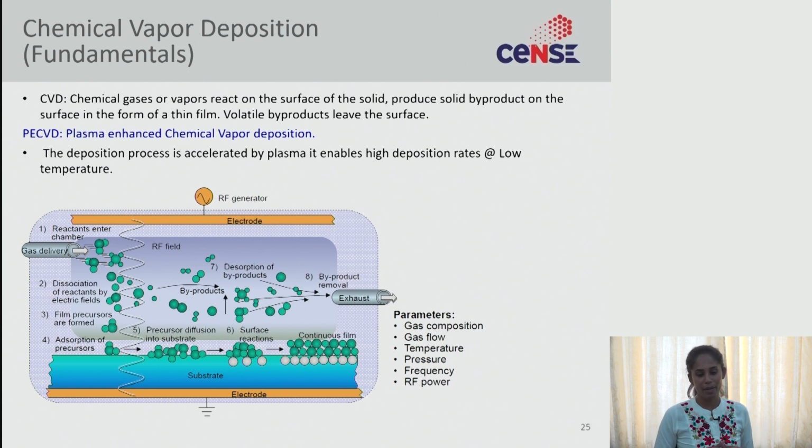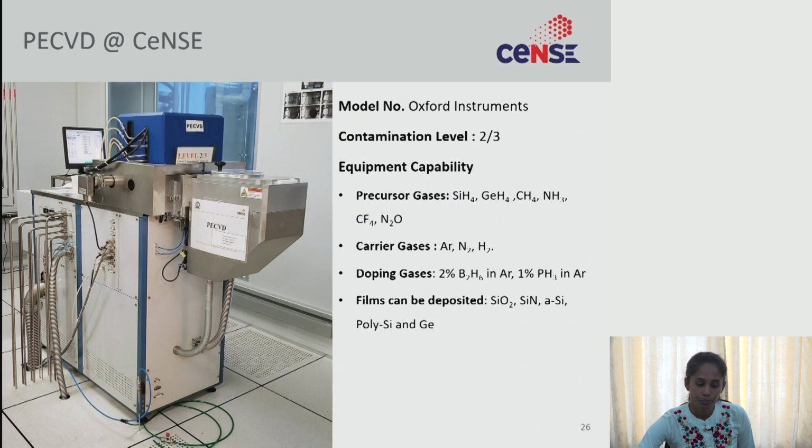Here again the different parameters can be controlled. In the process, the gas compositions you are using, and also the gas flow, temperature, at what pressure you are doing it, and also the frequency of the RF power you are applying, and also the RF power. Okay, and now